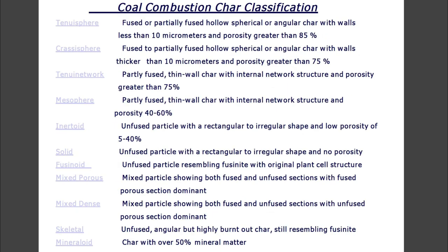The coal combustion char classification. Unisphere means fused or partially fused hollow spherical or angular char with walls less than 10 micrometers and porosity greater than 85%.